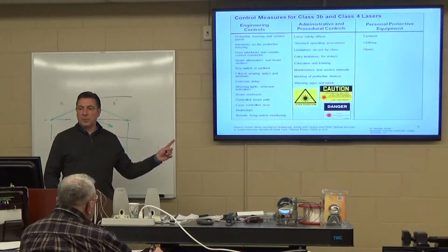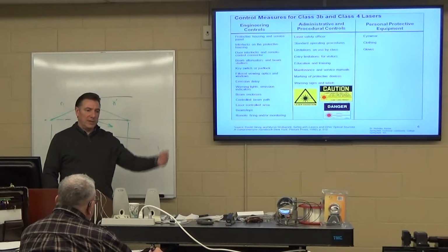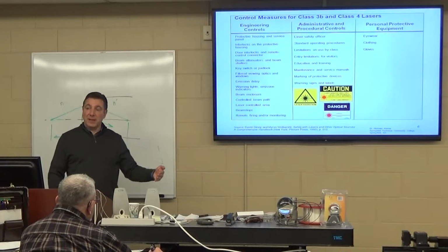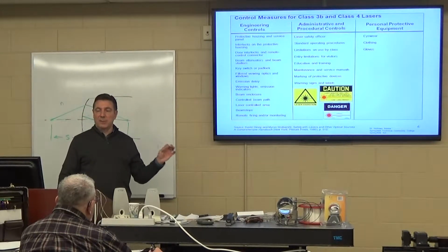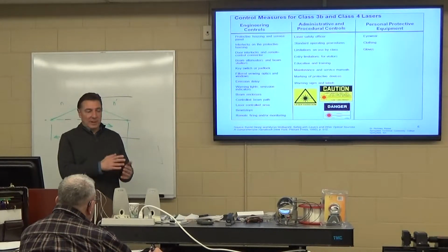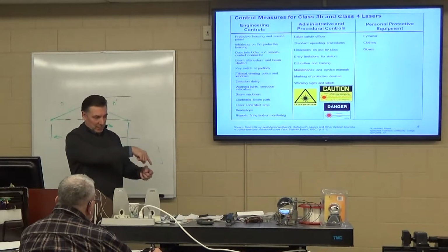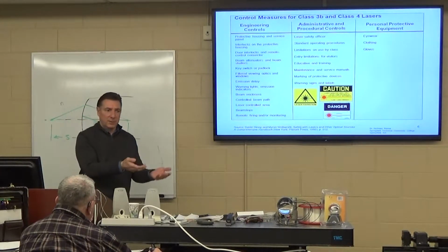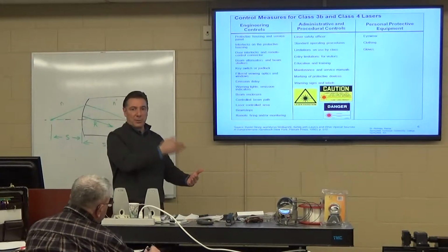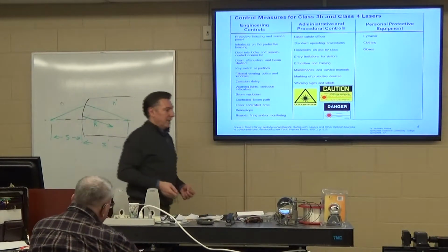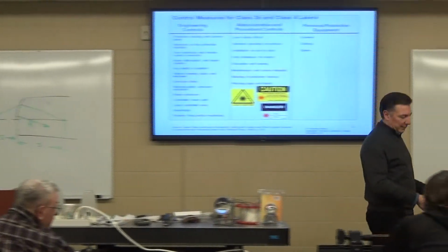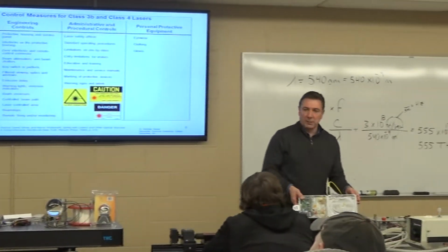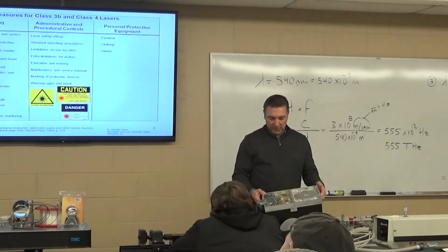If you look at the laser that we built in the back, it has this greenish glass in front of it. That glass is an optical filter designed for the specific wavelength of a fiber laser. So even though you can see the beam coming, as it's processing the material, the light doesn't come through. This is a fiber laser here, a 40-watt fiber laser that one of my students built a couple of years ago.